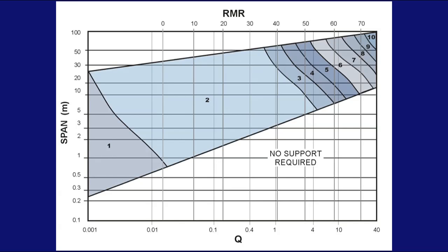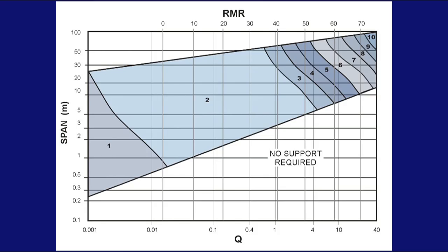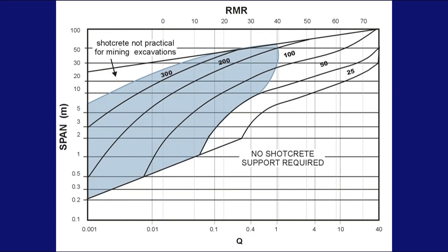Now, if we consider our real problem, we're looking at an excavation with a span of 65 meters. So we have our rock RMR value between 50 and 60, say 55 on average. And the span is 65 meters. So the recommendation for the bolt spacing is 6 square meters per bolt. If we look at the requirement for shotcrete, you can see corresponding with the 55 value and a 65 meter span, the recommendation is 100 millimeters of shotcrete. So those are the support recommendations.